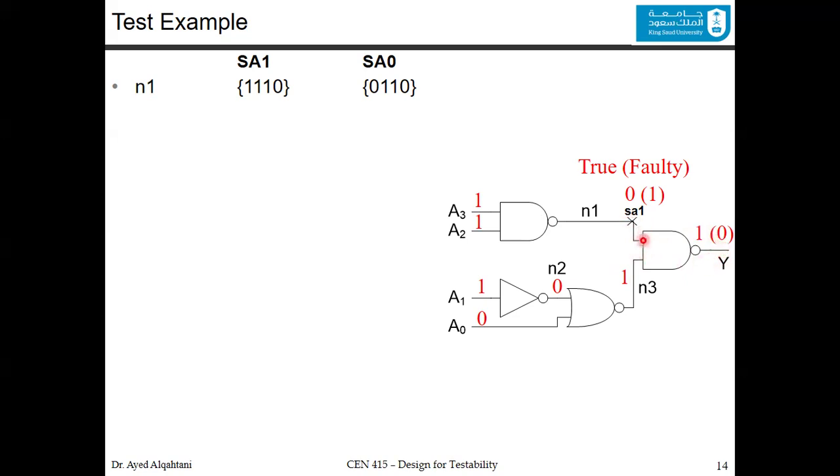The reason is because we have a NAND. This gate is a NAND. If you have a 0 here, let me write it down, and let me also change the color. If you say it is 0 here, then 0 with anything in the AND will give you 0. After the bubble, it will always give you 1, no matter what's the value here. This is why it's not appropriate to have a 0 here. And the reason is because of the behavior of this gate.